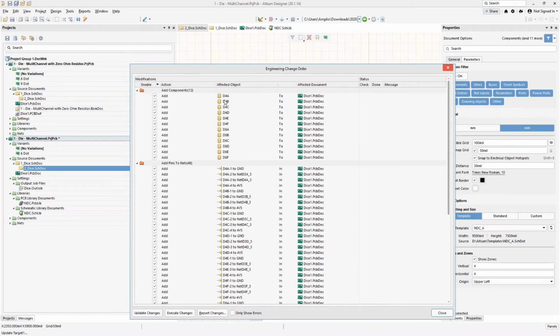And you'll see now that it's trying to add in those jumpers. I probably should have mentioned this to you, but if you really looked at the original part, the designator was actually JMP question mark. But notice how it actually picks up the designator of the original part. So with an alternate part, the original part still has some ownership of things, including the designator.